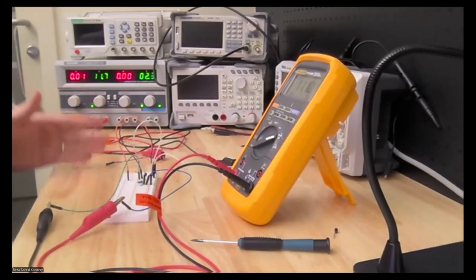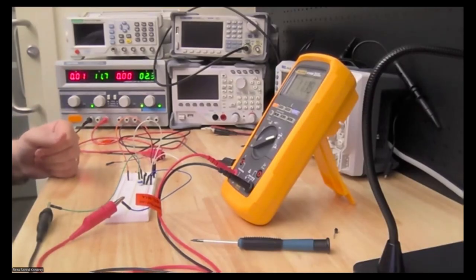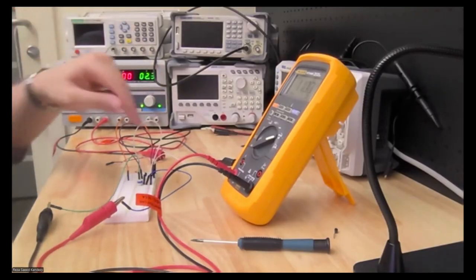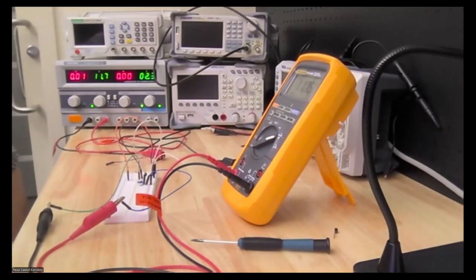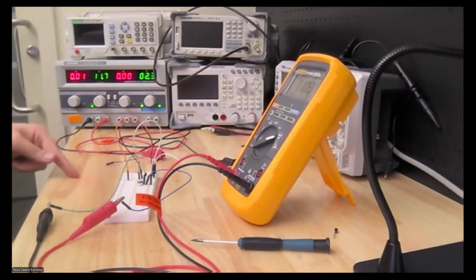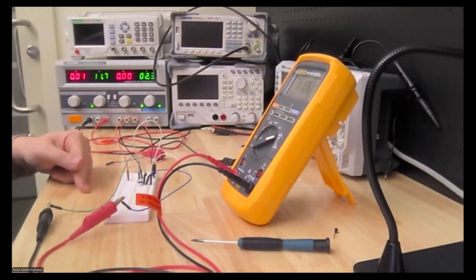For example, you set the voltage at 5 volt, you read the current injected into the base, and then you read the current that you get from the collector. Then you change the resistor, using the potentiometer, so you can see how the current of the collector moves by changing the V between the collector and emitter.